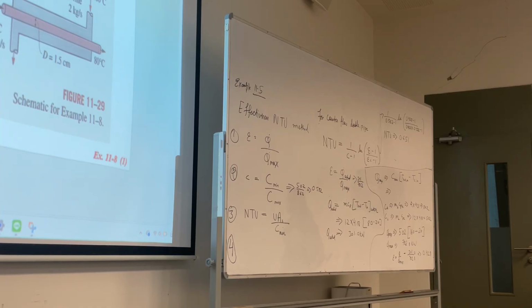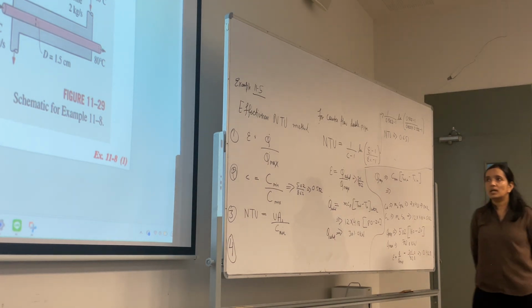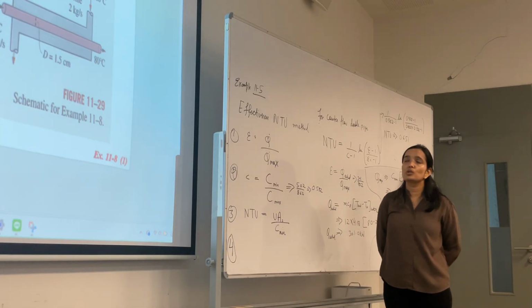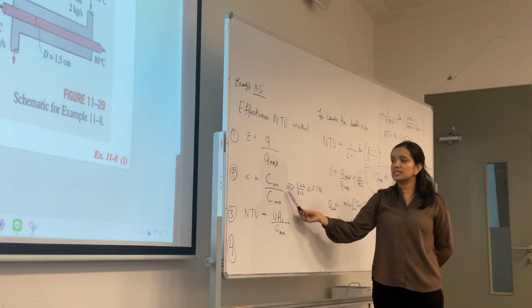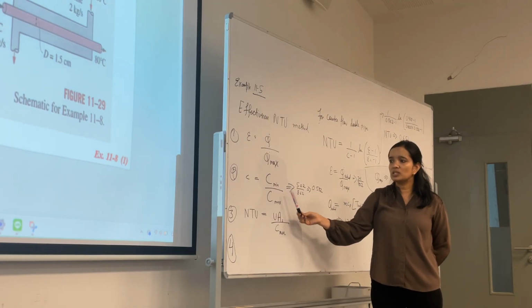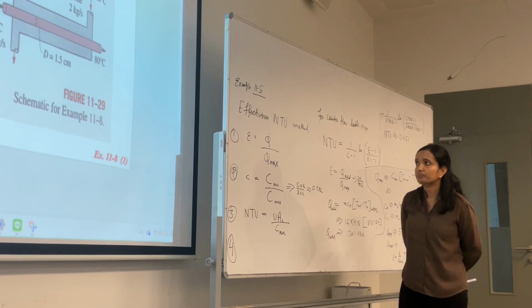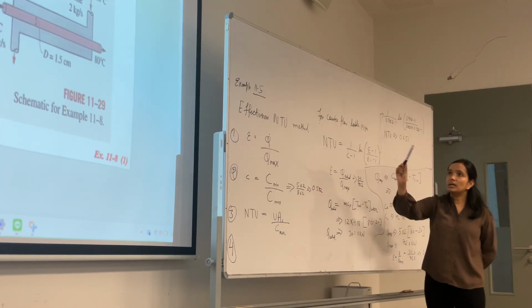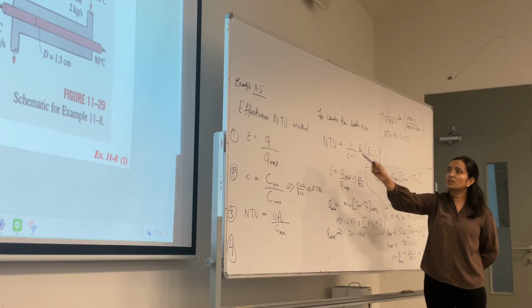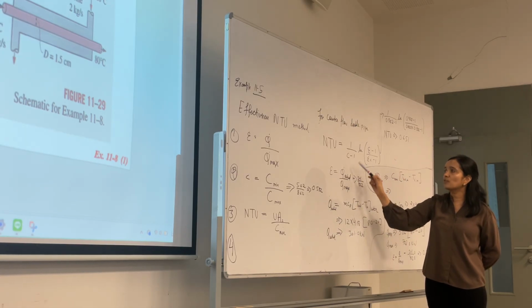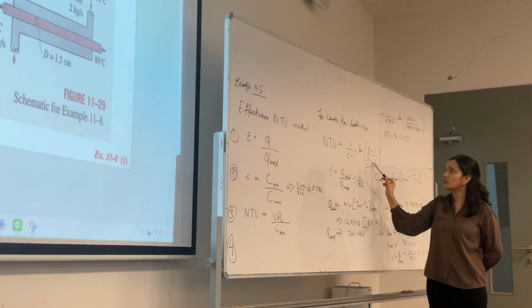I explain again. This is a counter flow, double pipe, asking length. And they have said that you need to use effectiveness NTU only. In effectiveness NTU, you have three non-dimensional units: epsilon, small c, and NTU. You go to the table and see for the double pipe counter flow, you have this formula. In this formula, I still need epsilon and small c.